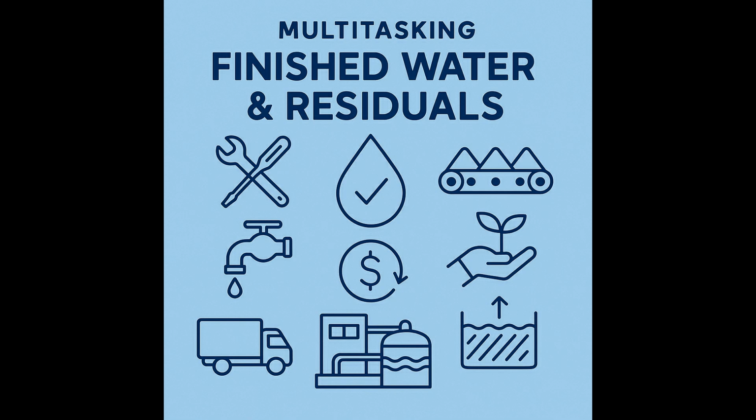All right, sludge handled. What's next for the water? Filtration. This step polishes the water, removing any tiny particles that didn't settle out, getting rid of that cloudiness or turbidity. Filters might be sand, anthracite coal, granular activated carbon, GAC, or even membranes. And filtration must create waste too.